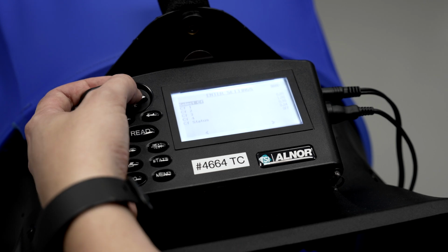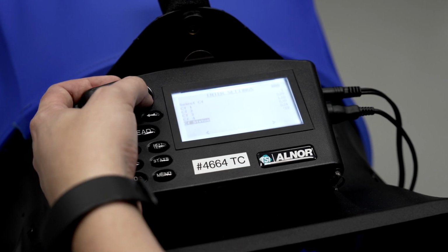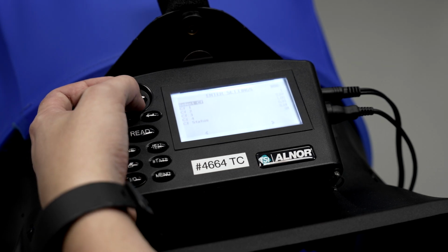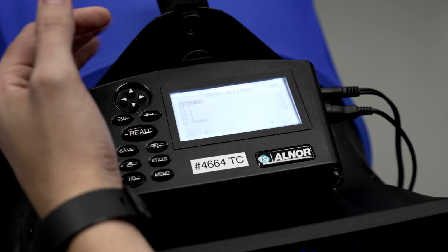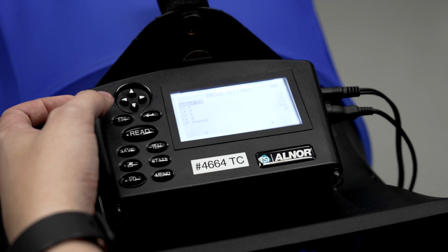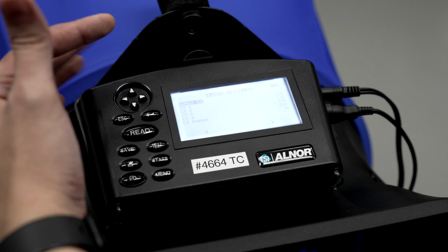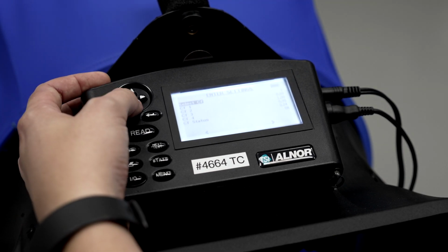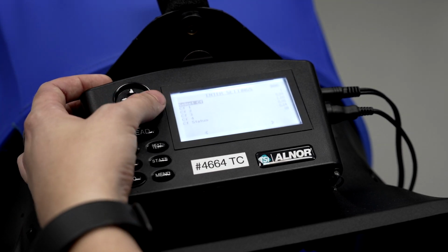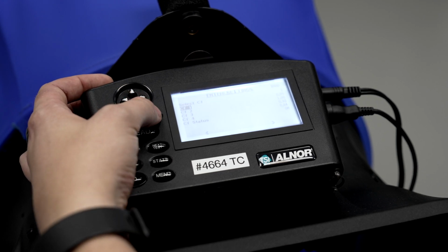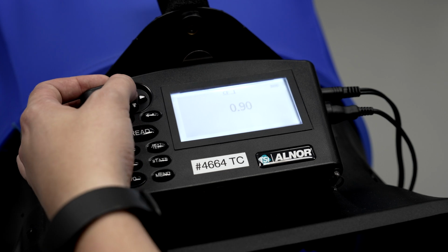Different manufacturers have different input methods. For this hood, we can choose which correction factor we want, and then we can assign the correction factor that we need to that number. With our airflows of 500 versus 550, our correction factor is a 0.91.